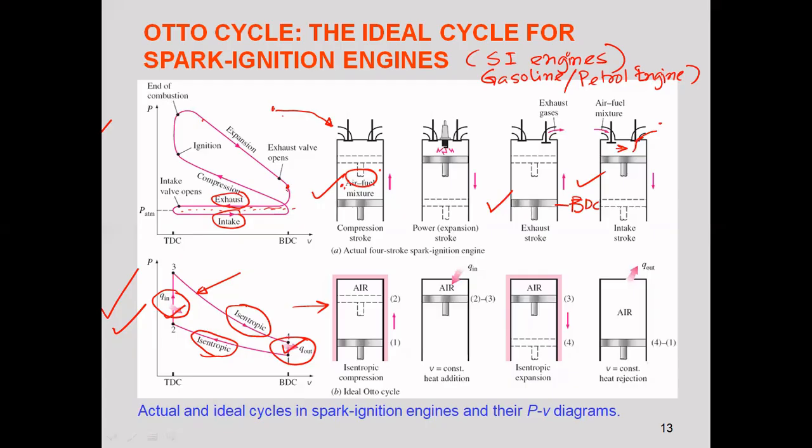The pressure will come down from this to this. Due to the high pressure differential, there will be immediate flow. But if the piston remains here, the remaining exhaust gas cannot be exhausted from the system, because the pressure is normalized almost at the atmospheric value.